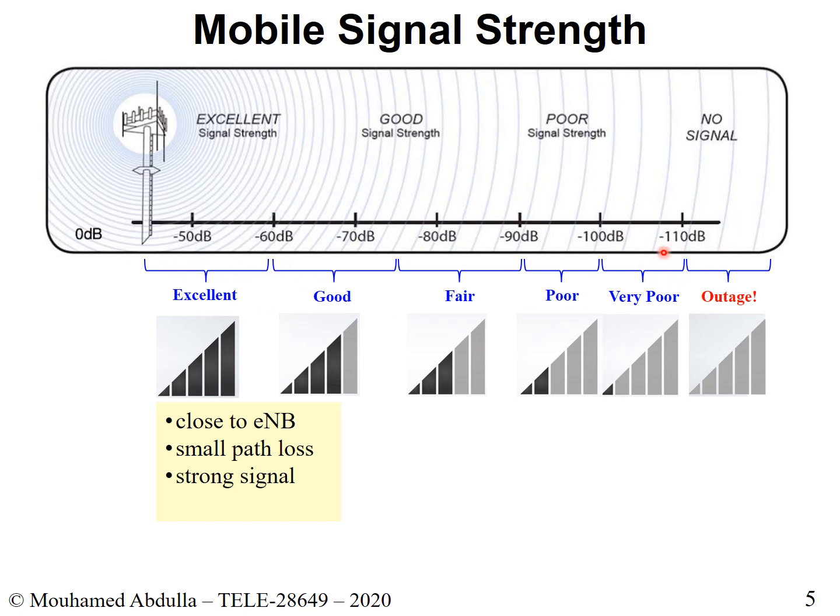It's like looking at degrees Celsius, right? If you have, I don't know, minus 25 degrees Celsius, that's very cold. And if you have minus 5 degrees Celsius, that's actually very hot. So it's kind of the same thing when you look at this. When you have minus 10 dBm, that means the value of your receive power is very small. Whereas when you see minus 50 dBm, that means you have a strong receive power. So this is kind of a review of how the dB scale works.